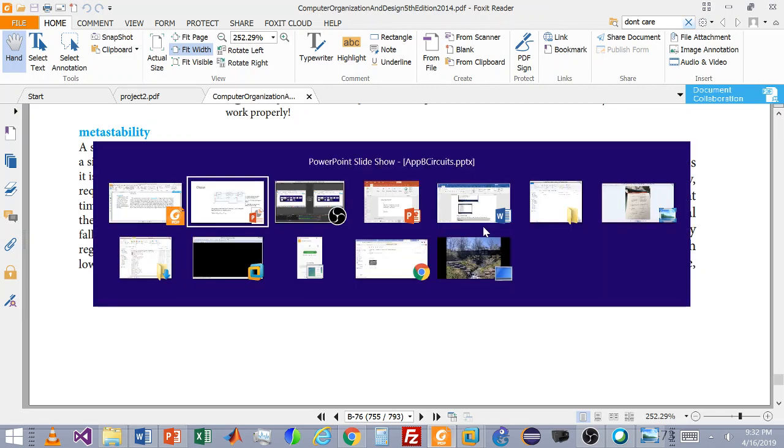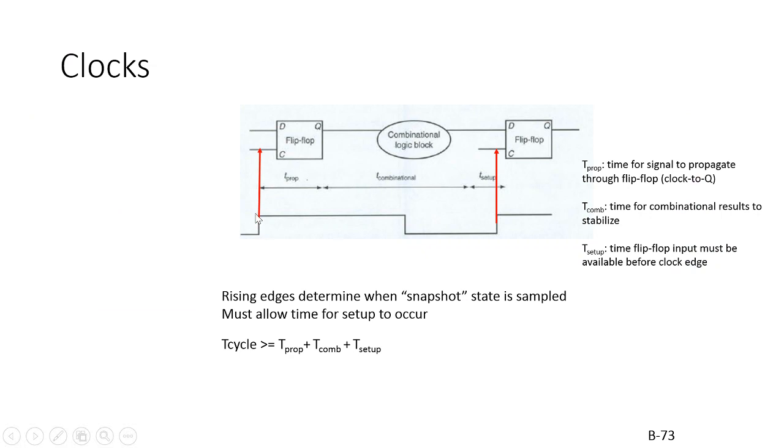In all these pictures, we always show this nice, pretty, it's there, bam, instantaneously. In real life, there's what's called rise time, so it's kind of like a sinusoidal wave, and fall time. So this isn't real, but depending on your time segment, it may be a realistic perspective. You need to be careful: if you hit this during its rise from 0 to 1, and we start the clock cycle right in between, you can have a metastability situation. So you kind of send a half voltage into your clock input.